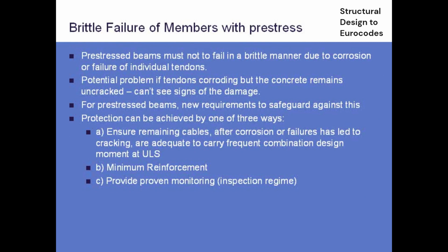What this is supposed to be around, there was some concern that with a prestressed beam, you may well have the tendons stressed and corrosion going on and you don't know about it, and the wires are busy breaking and deteriorating. But actually your traffic is relatively light, and although all these pre-stressing strands are going, the beam is actually just standing up on its tensile strength, the combination of the tensile strength and a bit of pre-compression. The concern is that suddenly you get a bigger load and the tensile strength is lost and you've lost so much pre-stress that suddenly all the pre-stress fractures and the whole thing just collapses in a brittle manner. Now, again, it's another one we haven't really worried about too much.